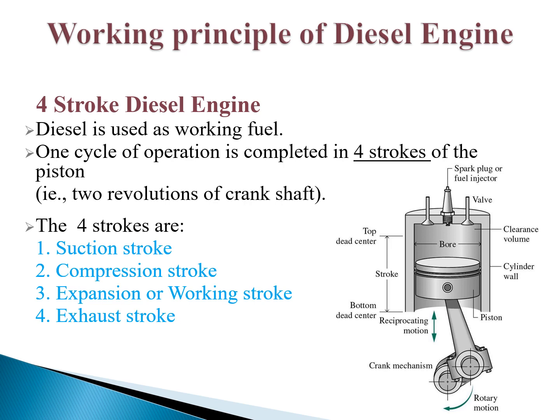The wall around the cylinder is known as the cylinder wall, and there is a piston inside the cylinder. This piston reciprocates from top dead center to bottom dead center and then from bottom dead center to top dead center. The piston is linked with the connecting rod, which is connected with the crank, and the crank is in rotary motion when the piston moves upward and downward.